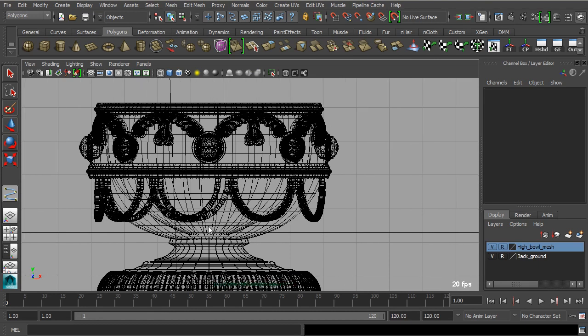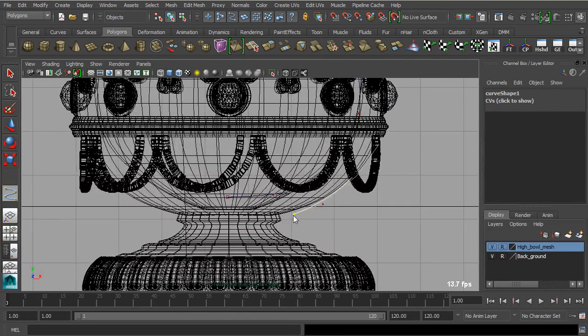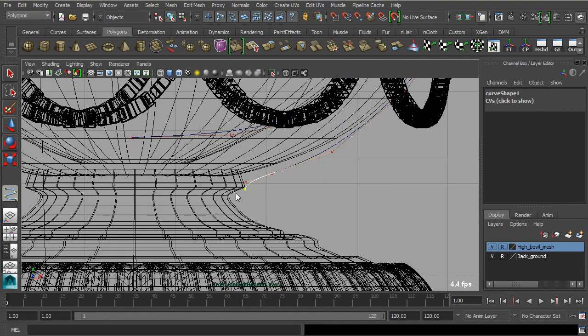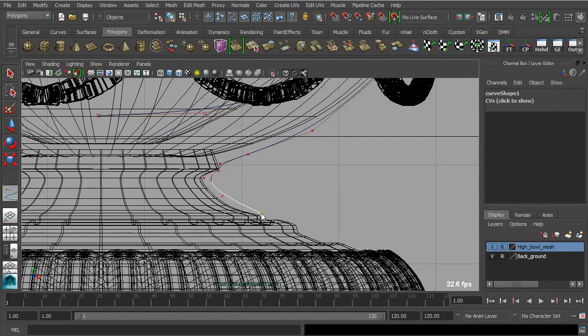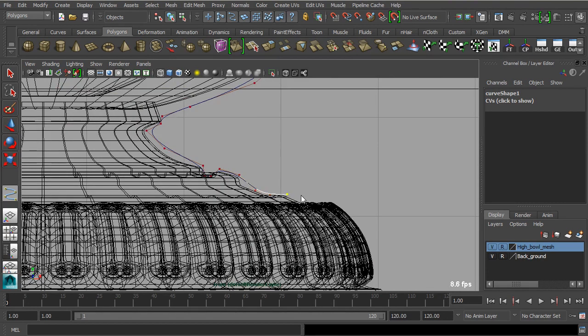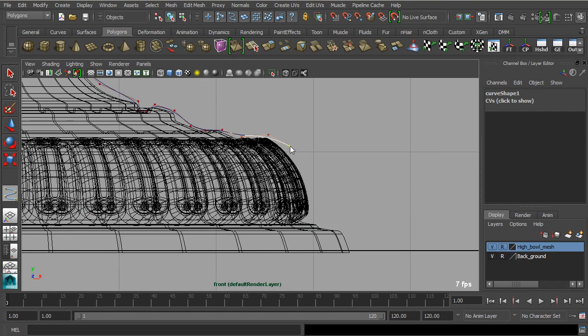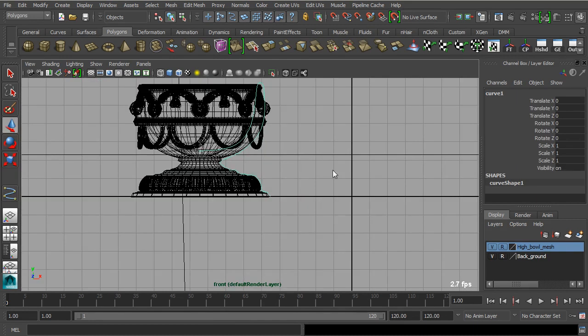Let's say I start from the midsection of this ball, and simply draw some curves while maintaining the gaps between them, because I know that at the end of the day I have to convert them into polygon objects, and for that I need to maintain equal parameterization, or you can say the topology. So I prefer to bring down those points, first of all to complete a perfect encapsulation of the high polygon object, and also to maintain the distance. But here in this region you can see that I'm losing the equal distance, and that's not going to be any problem. So you can just mark those curves and points in order to make the best low polygon model and to have the best encapsulation.